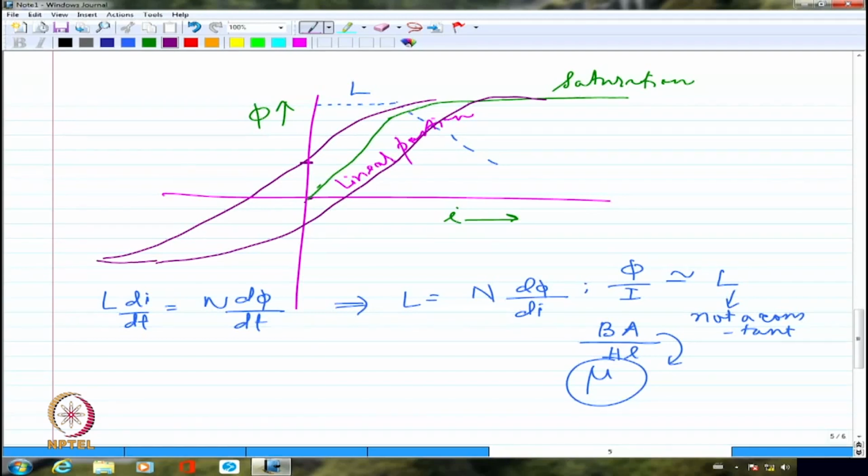Let's say I have 1000 amperes of current. I do have an ammeter only corresponding to 10 ampere. What I will do is to use a current transformer which will step down the current from 1000 ampere to 10 ampere. I can't assume that when I am actually coming to 10 ampere in the main winding, it will be exactly 10 divided by 100.